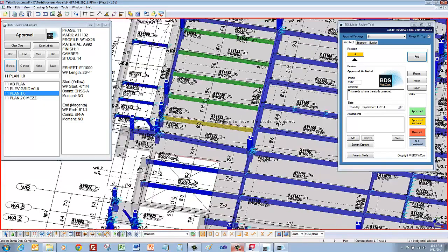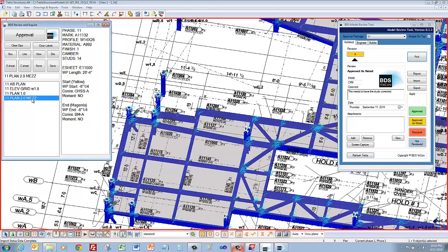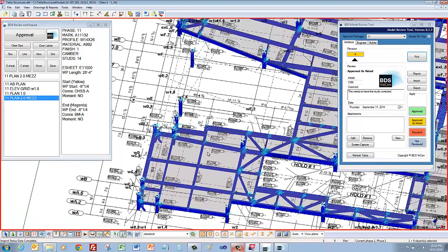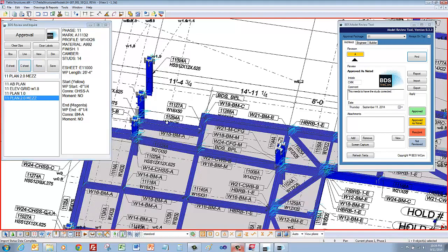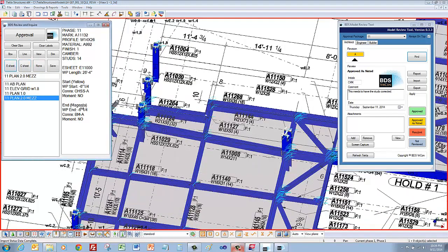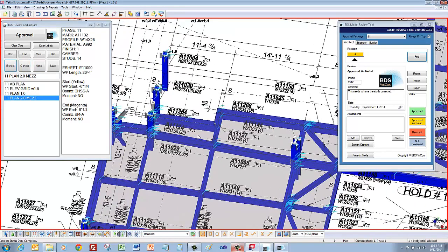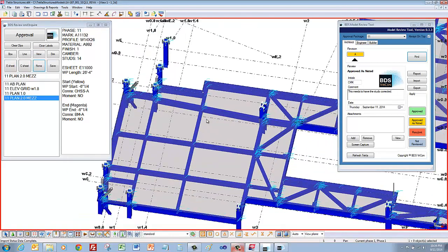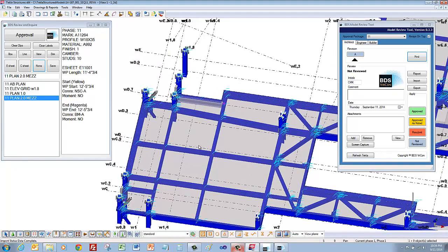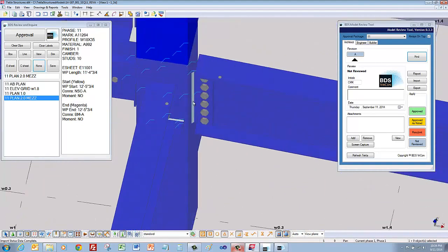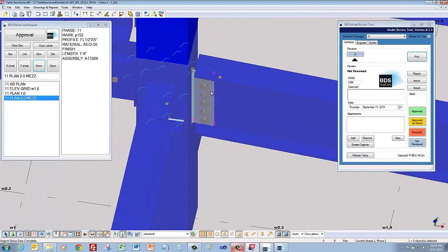Let's go ahead and review the next level. So we'll go to the mezzanine level. We're then clipped to that particular location in the model, and we can see the erection drawing by default. Again, we can just press C sheet in order to see the connection map drawing, and then E sheet to see the erection drawing. If we press none, this will then just clear out the model, and we can easily inspect and click on items here. Now again, if we wanted to review connection information more in depth, we can select on the bolts, the welds, and the parts here in the model.